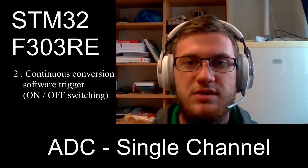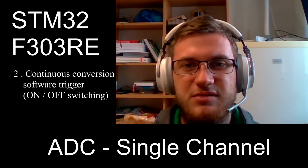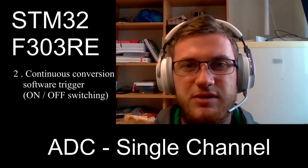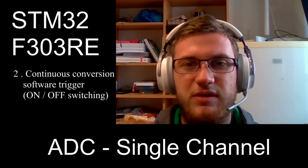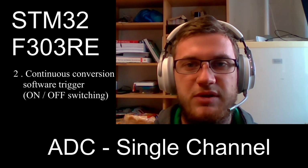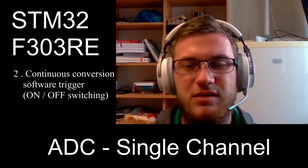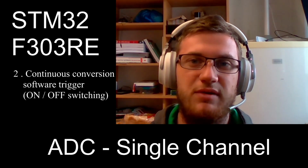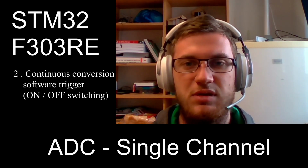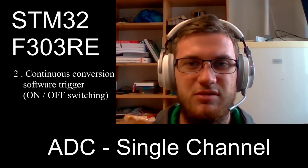The second method is continuous conversion and software trigger. This is quite a dangerous method and shouldn't be used that often, because when you start converting with the continuous conversion mode, the ADC will convert the values at the maximum clock speed of the ADC. We usually use this method in short bursts, when you set the ADC on and off, and in the short interval it will do a lot of conversions. The same as the previous method, this method by software triggering is more demanding on your code and CPU.